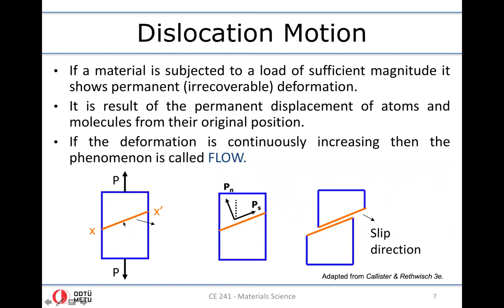All right. So in the two-dimensional representation, slip plane is denoted by this line, and slip direction is actually one of the directions, either in this direction or in this direction. So what you need to do is to check whether the external applied uniaxial stress can generate plastic flow. You need to decompose the stress into its component in the slip direction and component in the normal direction. Obviously, slip is based on the shearing, and therefore the most important component that governs the plastic deformation is the shear component that is denoted by PS.